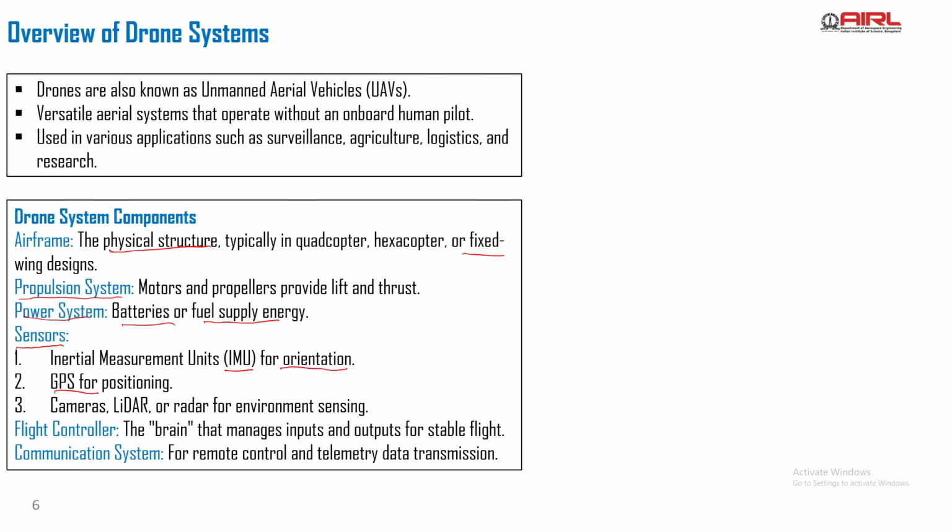In addition to IMU and global positioning sensor, you have cameras, you have lidars, you have radars. Camera can be used to understand the context where the drone is present, right? A lidar can just help you. For example, you can use a single point lidar as a height sensor, or even a single point lidar to find out the distance to a specific point, right?